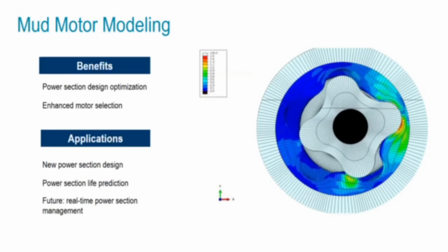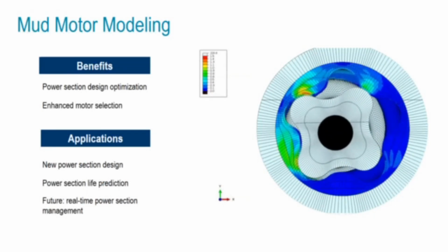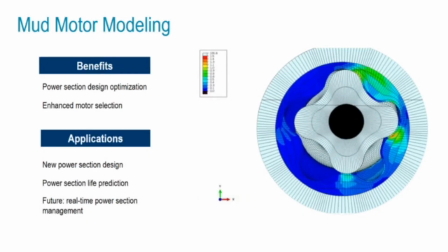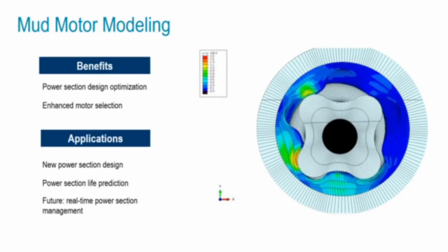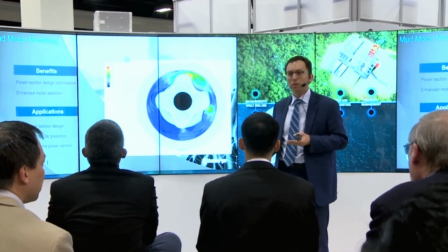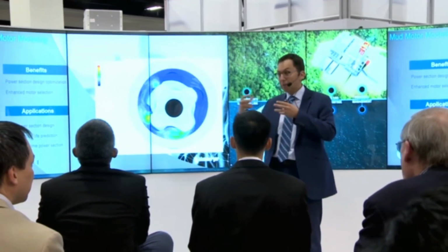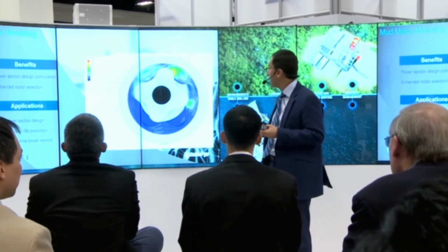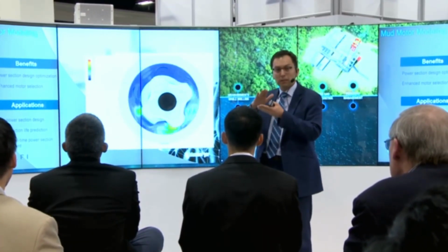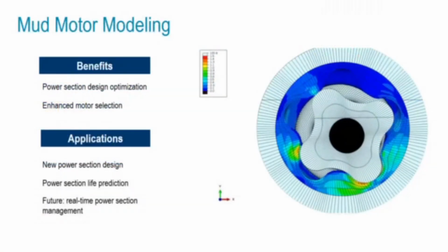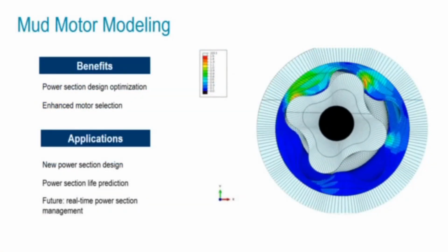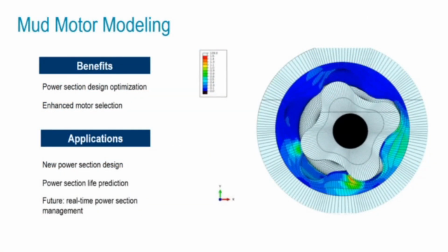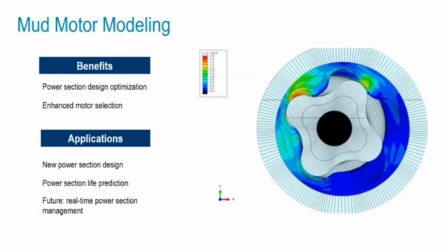We have a rotor stator that goes through a 3D profile along these contact lines, and that's what makes the seal for us to produce the power. This is a very complex phenomenon, so we have modeled all of that. The contact between the rotor and the stator also is quite complex. You see the deformation of the rotor. You will experience variable friction factors as these happen.